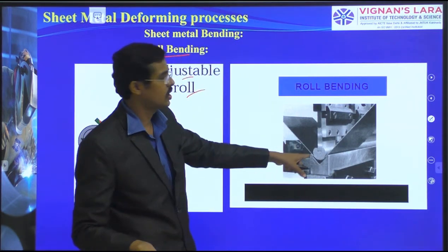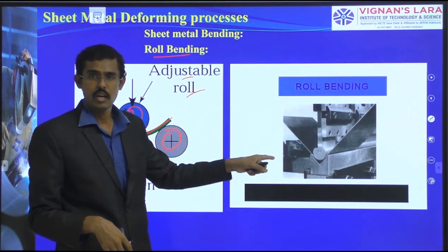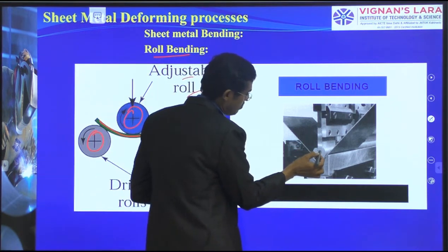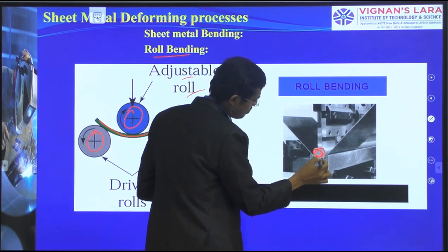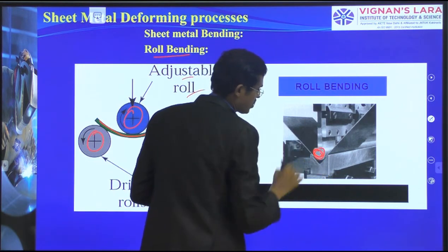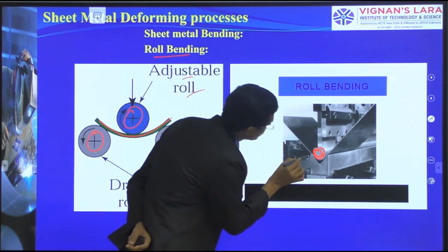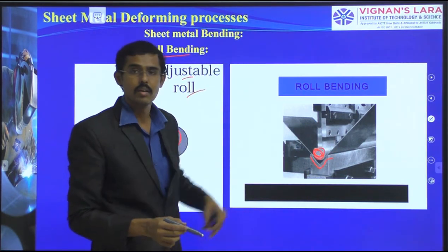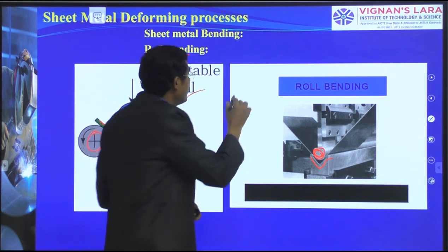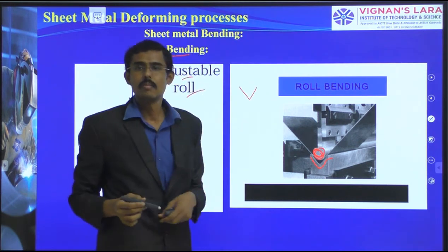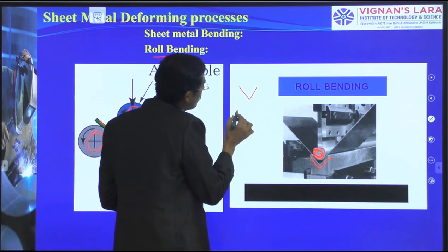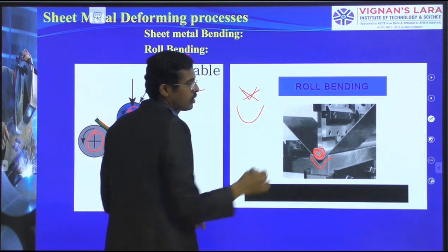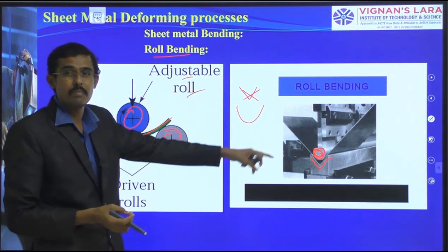So see, this is the original industrial image showing the machine setup, containing the roller. This part is the roller and we are going to press. So this is the die, you see, the die contains the V shape, but the punch is a roller. So somehow we will not get a sharp product. We will get a slightly ball-shaped product, even with the combination of die and punch.